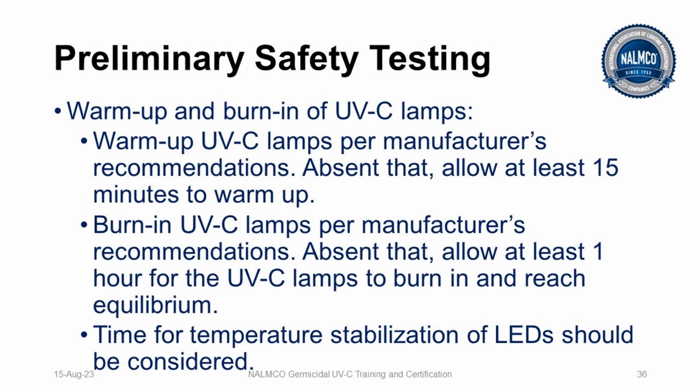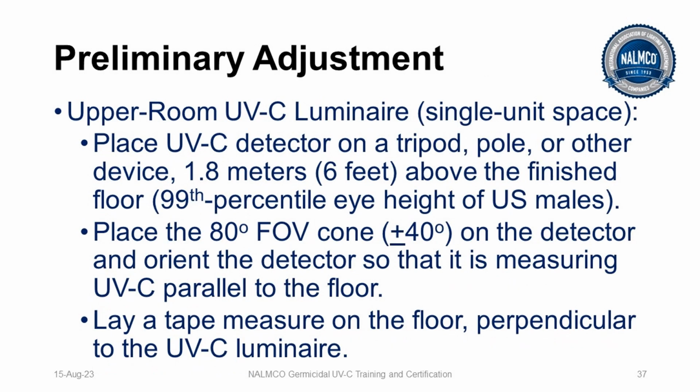If the manufacturer does not give a recommendation, then allow them at least 15 minutes to warm up. Burn in the lamps per manufacturer's recommendation. Absent that, allow at least 1 hour for the UVC lamps to burn in and reach equilibrium. Time for temperature stabilization with LEDs should also be considered.